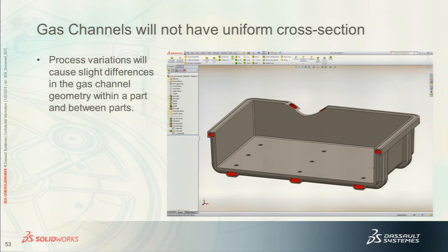And depending on where your gas channels are, your gas pins would have to be located for your particular design. That would be best left to the molder that you would use that is familiar with the gas assist process. Let them get involved in helping you mold the part.